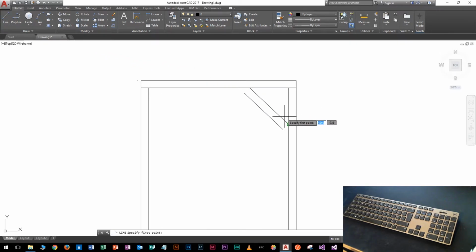I could fall into the trap of measuring down 100 millimeters here, but I'll just show you what that looks like. It actually won't give you 100 millimeters across the timber. It's measuring down, which means that it'll be less. So that is of no use. So that's why I'm using offset, because it gives me a true 100 millimeters timber.